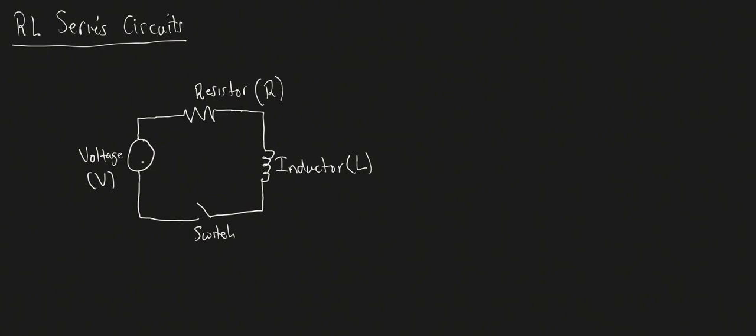If you just have a voltage and a bunch of resistors, depending on whether they're in series or parallel, you only need basic algebra to analyze those. But when you add other components like inductors and also capacitors, which we will see in the future, and you want to analyze it from a purely mathematical standpoint, that's when you need differential equations. So we need to get a differential equation out of this.